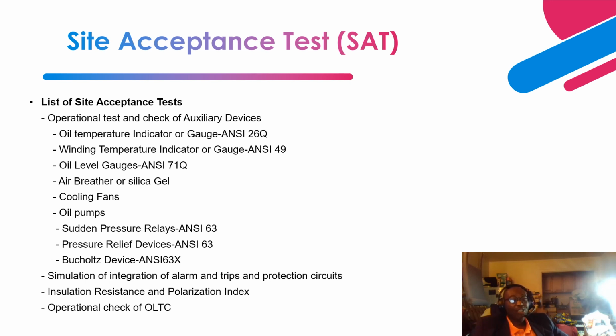The next check you want to do is the air breather, the silica gel. Make sure that it is filled with the required silica gel and that it is the right color.